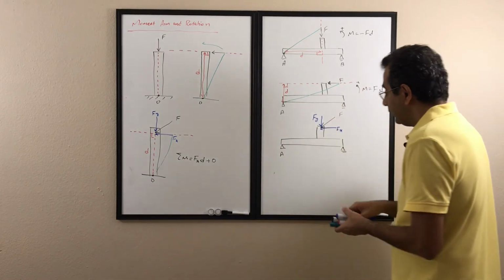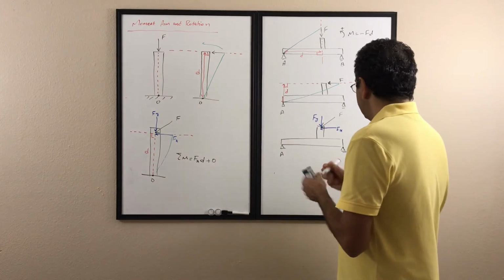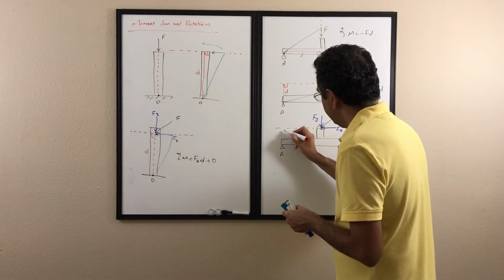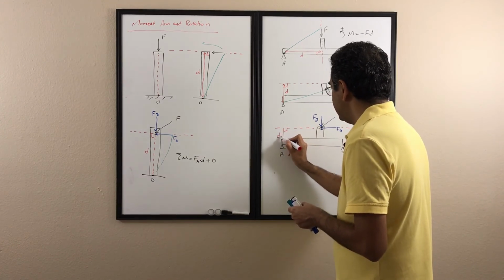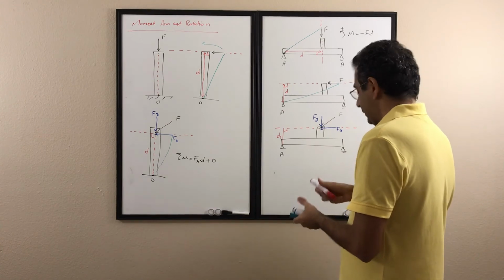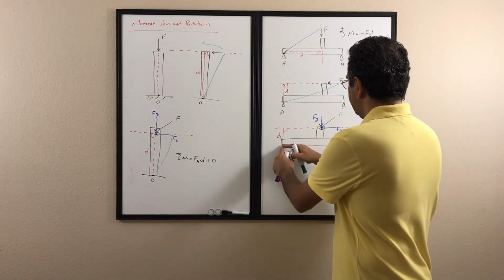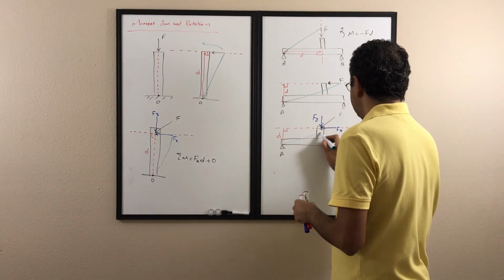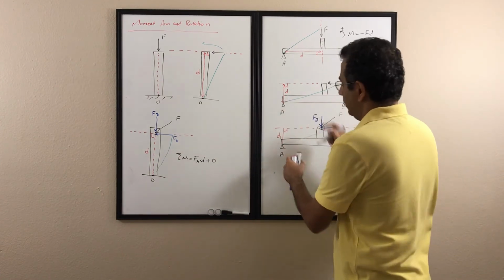Now I can find the moment for this force. I start with Fx. For the moment of Fx, extend the line of action, and then draw the line that is perpendicular to the line of action, and assume that's D1. Which direction is it going to rotate? Assume there's a rope connected from A to the end of Fx, and it rotates that rope counterclockwise.